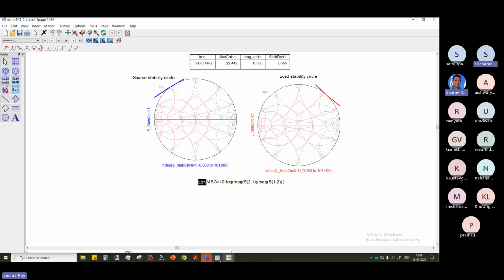See, because we are adding a resistance, obviously we have to give away something. What we are doing, loss. We are actually giving up some amount of gain. If the amplifier, or the transistor, was itself stable without anything, it would have given us better gain. Because we are now putting some resistance here to make this stable, we have to give up some gain. That is what we are doing. So if you want to put more resistance, it will reduce the gain even more. That's why we stick to this boundary zone region.